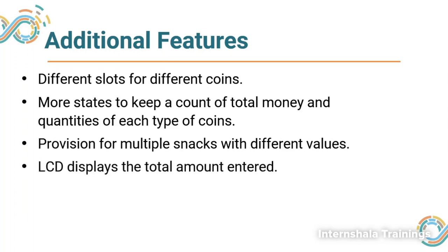And the LCD will display the relevant information like how much total amount is entered, how much change will be returned, and all these things. You can also display that I have selected a candy bar or a chocolate, so that there is no confusion that I selected a cola and I am given a chocolate, because both of them had the same price. So all these additional features as a designer you can have and keep expanding your finite state machine diagram.